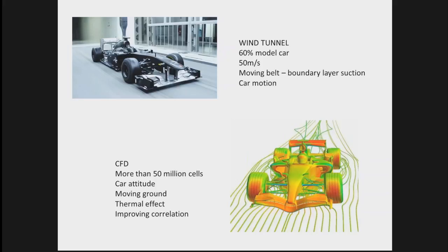And the other thing is the car motion system. Effectively in the wind tunnel, the car is moving around to simulate different attitudes of ride heights and steering angle and yaw and roll angle. And it's fully automated now in wind tunnels. Now CFD has grown over the last 15 years, let's say, and it's become a major tool for us as well.